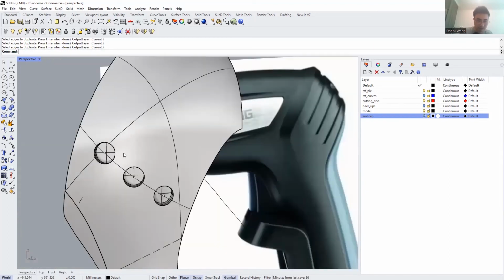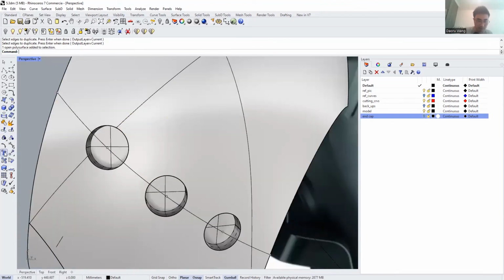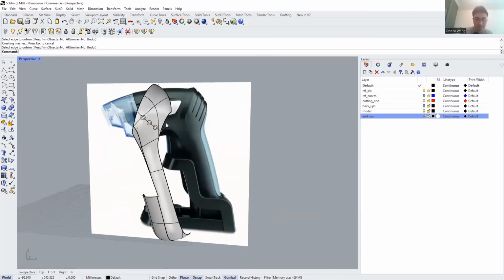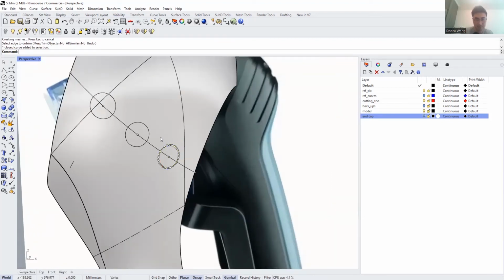So I got the surface, and then I want to make the surface back to what it looked like before. I will just come over here and right click this. Left click is trim, right click is untrim. I will untrim this, click it, and click it. In that way, we only take the circle, instead of really doing anything to the surface.